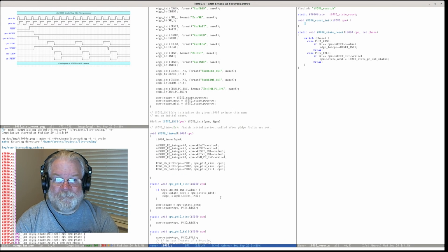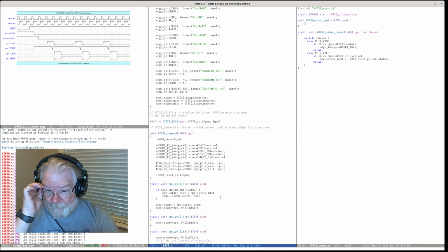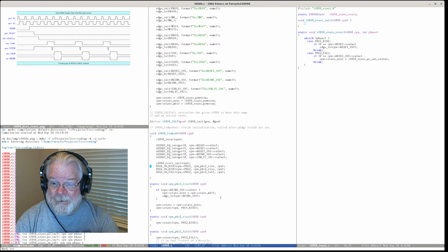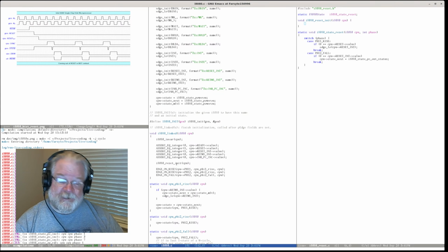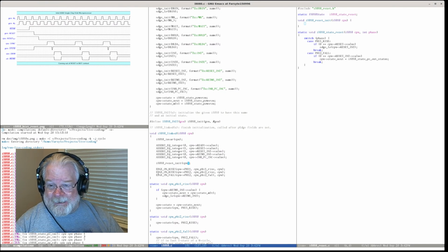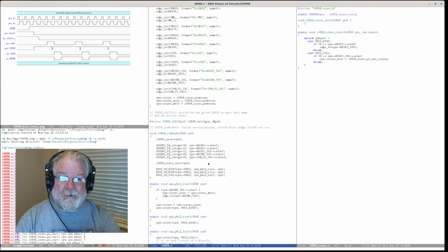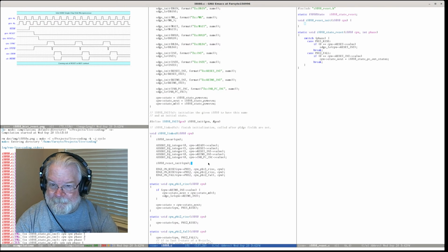Got all that set up, and we say i8080 reset init CPU. We could actually do that before establishing our edge handlers. That way, if reset init mucks with any signals, just in general, reset your submodules and then establish these guys. And this guy can muck with all the signals he wants during his initialization without triggering any of this. Hopefully he doesn't, because that would require incrementing tau, and we don't want to increment tau during this. But let's keep it clean.